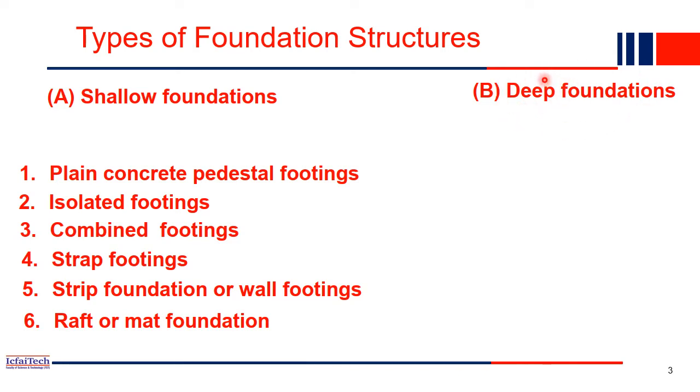If the soil quality is very good, like in Hyderabad, the soil condition is very good. You can see the bedrock is very near to the ground surface, and in some positions, the bedrocks are actually exposed to the ground surface. Because of that, soil quality is very good, then we may not go with the deep foundation. So shallow foundation is also sufficient in that case.